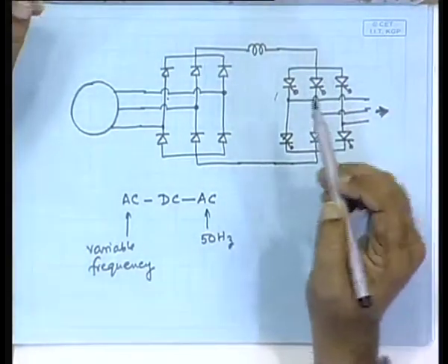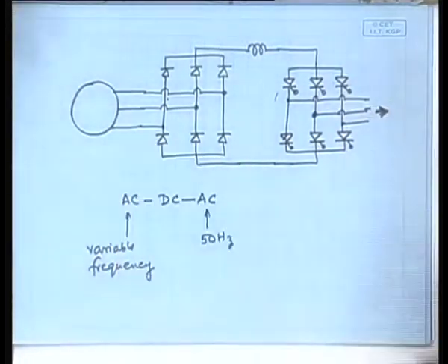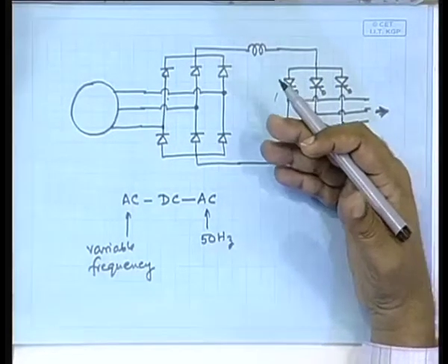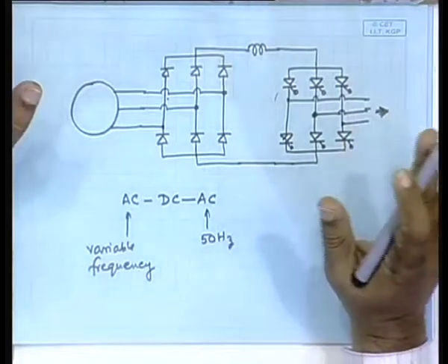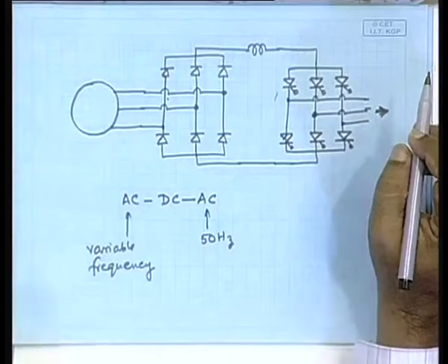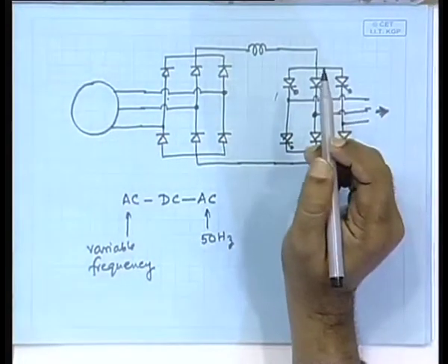In this way, it is then possible to vary this speed by any extent, right, and that is why this is sometimes being preferred, because here there is no restriction on the speed that you have, the AC DC AC system, and in that case you can use a synchronous machine.